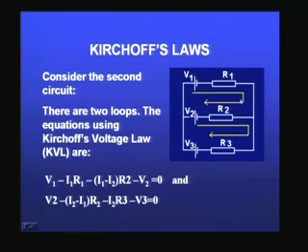So, they are connected in this way, and now you can see you have 2 loops. There is one loop in this direction, as you can see on the screen, and there is another loop here which involves V2, R2, R3 and V3, right. So, if I now try to apply Kirchhoff's law for this, then you can see V1 minus I1 R1 minus (I1 minus I2) R2, because I assume the current here is I1, here it is I2, here it is I3. So, I2 minus I1 is the current flowing through R2, minus the V2, that should be equal to 0.